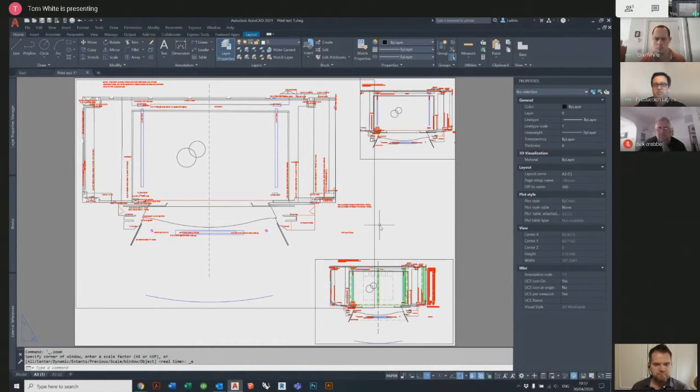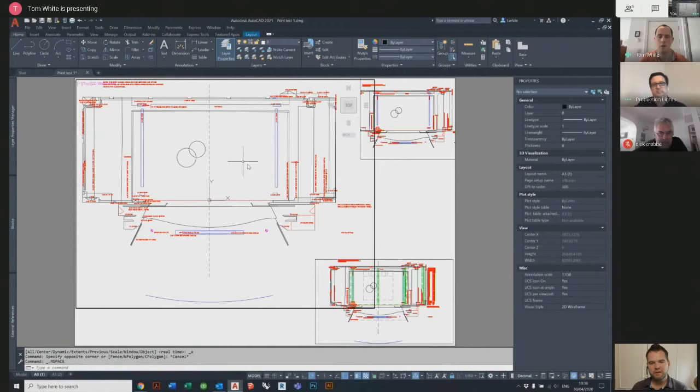So Tom, when you're producing a paper space and you want to highlight certain areas, is there a quick way to sort of just quickly, like in Dick's case, if he just wants to show the speakers and sort of grey out everything else, is there a way to do that? Yeah, so I'm going to double click in this main viewport, which is locked. I just want to check that it's locked.